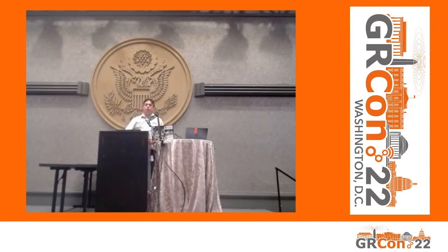With libIO, you can run libIO today on your x86. Lots of notebooks actually use IIO for the gyros or for various other things. And libIO has this remote backend mechanism. So you use libIO on your x86 system, but it can magically connect to a remote backend that runs on an embedded target, and that's being used heavily in all these examples. So you can connect to your FPGA platform or your Raspberry Pi and have the IO devices on your x86 system, just like they would be local to your embedded system.